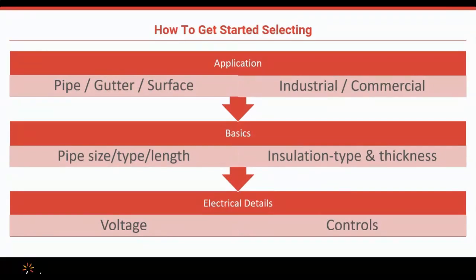And also if it's a hazardous location, it's really important to understand what the area classifications in that area might be. A Class 1 Division 2 area, as an example, is what we handle all the time with our industrial components, standardly rated for. But if you get into an explosion-proof area, Class 1 Division 1 area, that becomes a completely different product offering that's rated for that application.